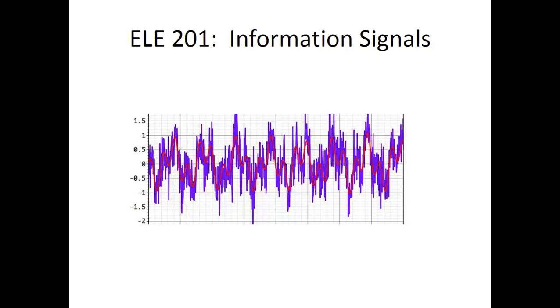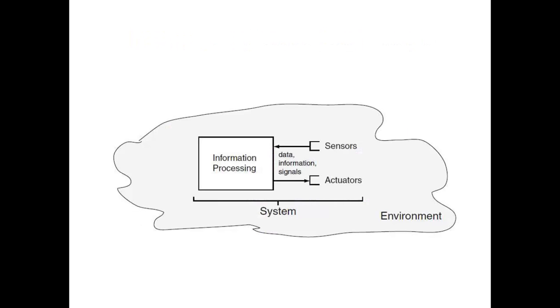Technique where you don't do an average, meaning a mean, you do a median. This is a median filter. And this actually will remove outliers. If you have glitches that are really big, big outliers from your main signal should have no effect, the median will kind of get rid of those. All right. So that's a nice, useful technique that is not actually addressed by the mathematics we're going to learn in this class. So there are limits to what we'll learn, but it's also very, very broad.